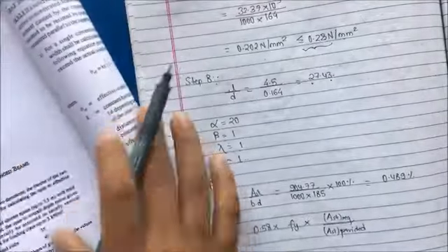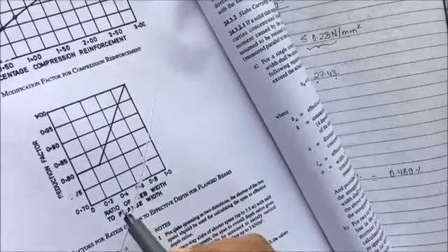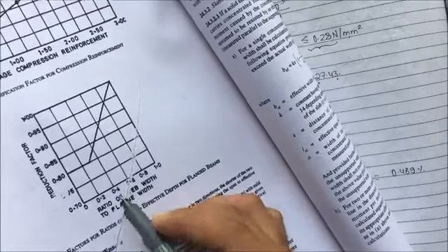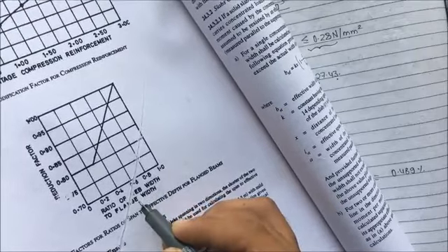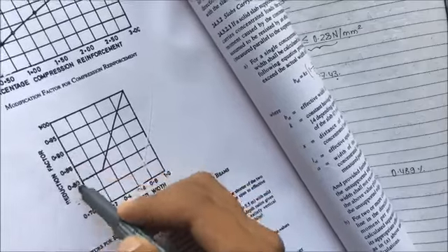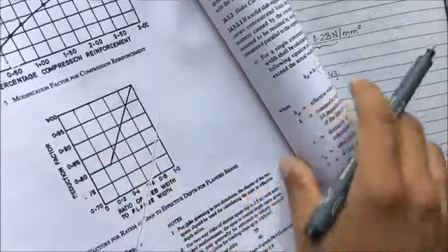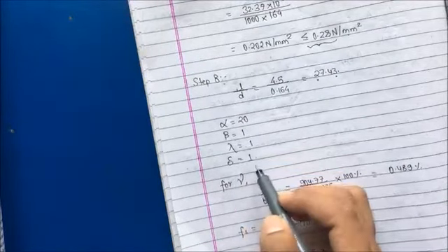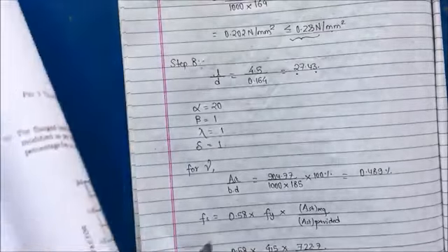Similarly, for delta, we have to use this graph and the ratio of web width to flange width. We are not providing any flange section, so the ratio of web to flange width will be 1, for which the value of reduction factor will be 1. So alpha is 20, beta is 1, lambda is 1, and delta is 1. But for the value of gamma,